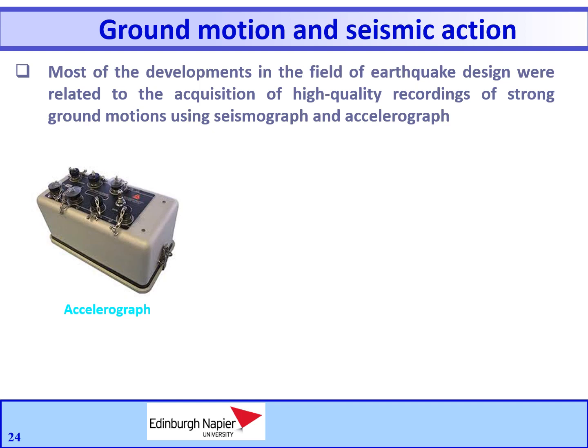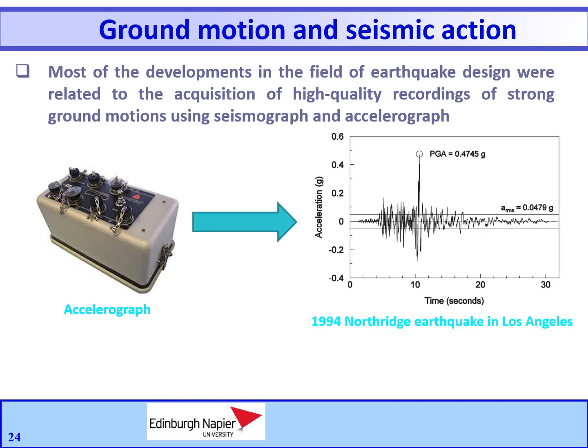The motion to be measured generally varies arbitrarily with time and may include many harmonic components covering a wide range of frequencies. There are closed-form solutions giving the displacement of the instrument mass relative to the moving frame, and then computations can be carried out by discrete Fourier transform procedures to obtain the actual ground acceleration.